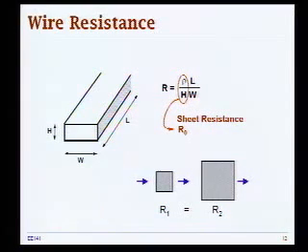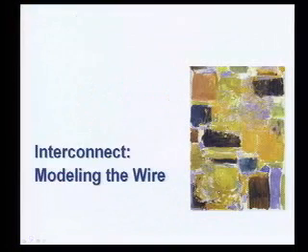People have already transitioned from aluminum interconnect, and now copper interconnect is widely adopted in semiconductor manufacturing, and there is basically not much more room to go. So you have to really start scaling technology in a way that you keep the wire height constant. And this is also an interesting illustration that all you care for here is basically this sheet resistance, this resistance per square. So a wire of this geometry over here would have identical resistance as a significantly larger wire shown on the right hand side. So that's important to keep in mind.